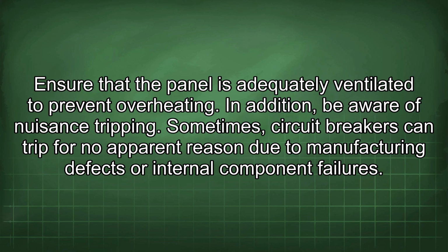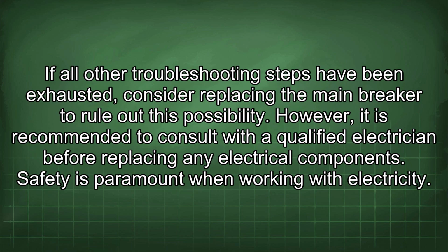In addition, be aware of nuisance tripping. Sometimes, circuit breakers can trip for no apparent reason due to manufacturing defects or internal component failures. If all other troubleshooting steps have been exhausted, consider replacing the main breaker to rule out this possibility. However, it is recommended to consult with a qualified electrician before replacing any electrical components.